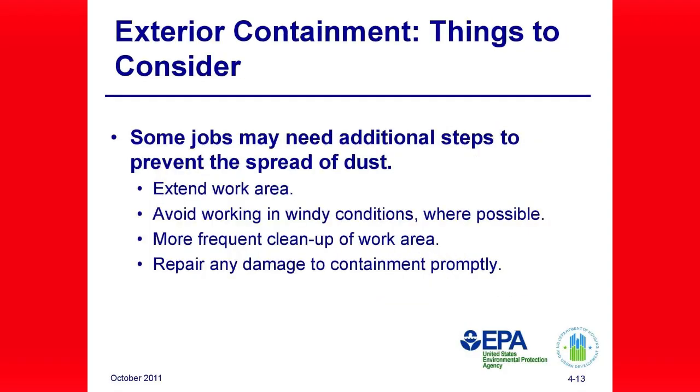Exterior containment, things to consider. Jobs needing additional steps. Some jobs may require additional steps to avoid the spread of dust to the rest of the property or to adjacent properties. These jobs might include work in high winds that can carry dust out of the work area, and work conducted on upper levels of a building during which even light winds can spread dust beyond the containment as it falls.